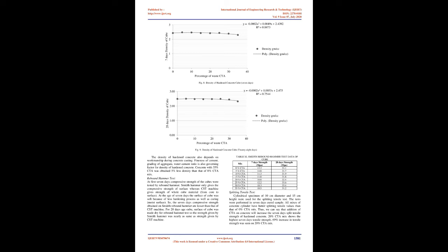Sand. Sand used for the tests was obtained from suppliers located in Kotra. The tests performed are listed as gradation. Sieve analysis of sand was done to find the grading zones. The sieve sizes used were 10 mm, 4.75 mm, 2.36 mm, 1.18 mm, 600 microns, 300 microns, 150 microns. The tests were performed in accordance with IS 2386 Part 1. Grading was done based on Table 4 of IS